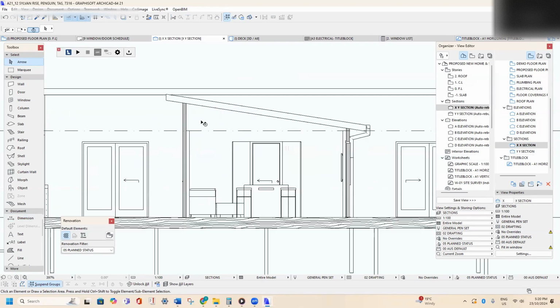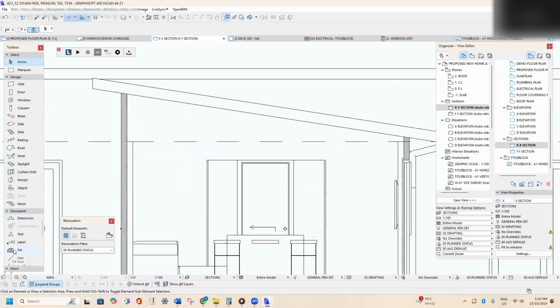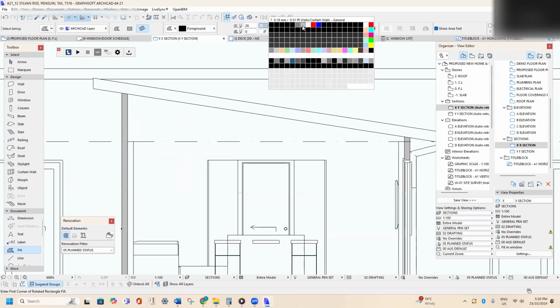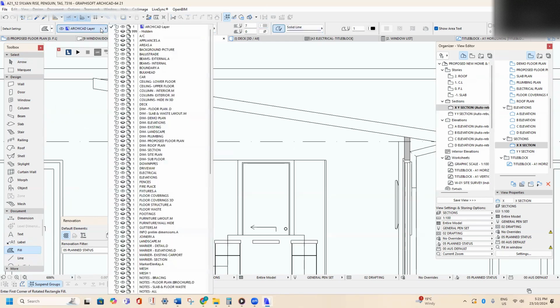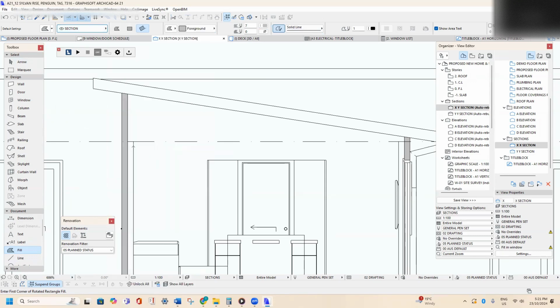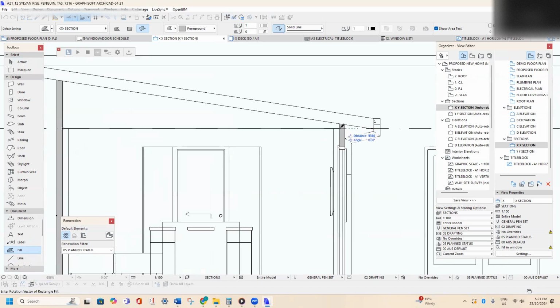At this point, we'll show the roof space as a flat ceiling. So if you click on the fill and click up here and change it to foreground, and then change this to light gray. Change the layer to S. If you type in SE, you'll find section. Click on it, click, click, drag it up 90, enter, enter, press escape.